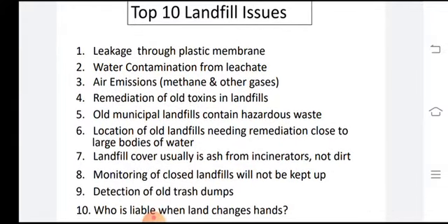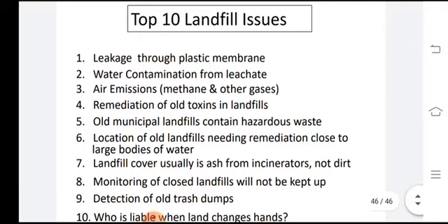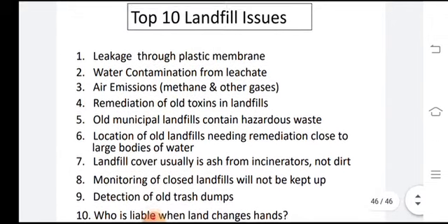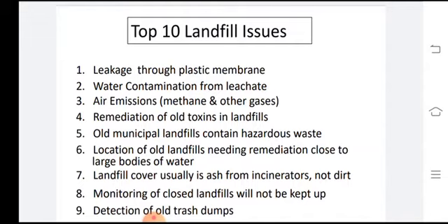At the same time, while talking about the landfills, which is one of the most important features dealing with the environmental issues, we are more concerned with the proper designing of the landfills, which must contain the gas recovery system, which must contain a leachate collection system, which must contain a monitoring system for both gas emissions as well as the leachate being percolated down into the soil as well as the groundwater. So that's how we will be dealing with this landfill topic. Again, it's important because it is dealing with soil contamination.